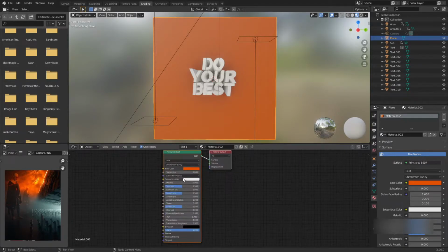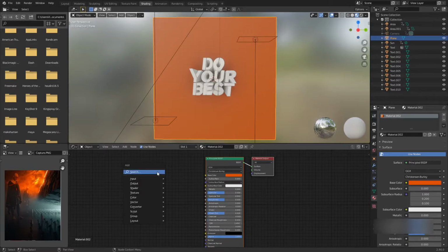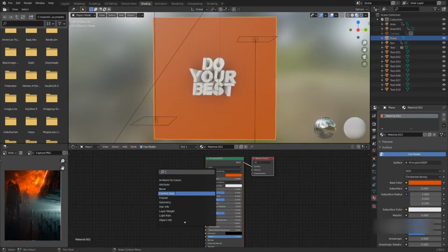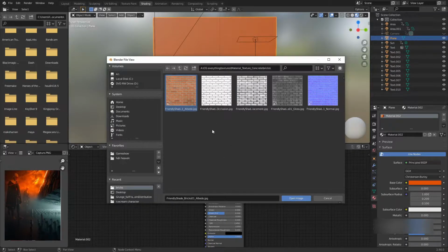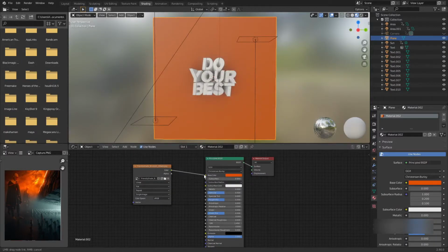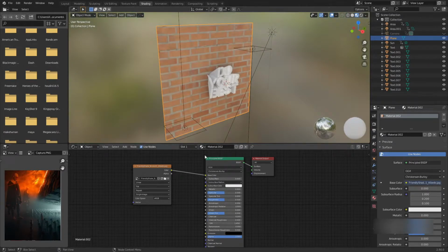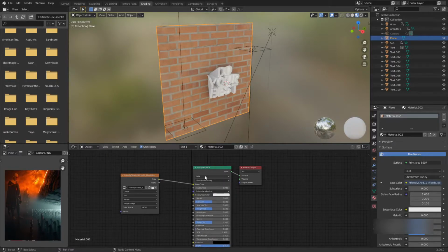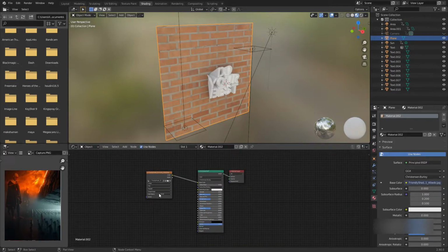You can create any look you want basically. So for shading in Blender, you can do it manually just by doing Shift A and looking for a node that you want. And the most used node is Image Texture. With this node, basically, you can open up an image. In my case, it is brick, and all you have to do is plug it into Base Color. And as you can see, we have our brick texture plugged into the color of this BSDF. So this is one of the main things you can be doing: doing Shift A, looking up a texture or a node, and playing around, mixing them, and so on.